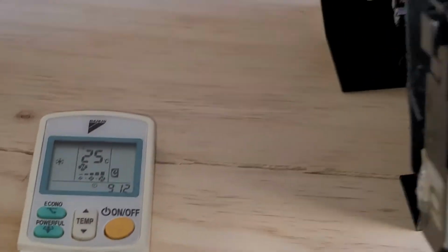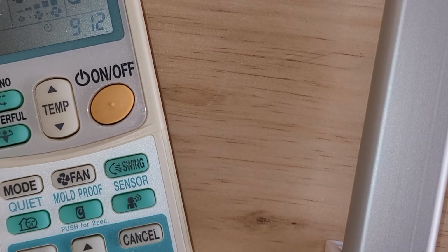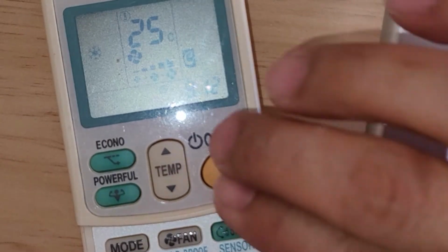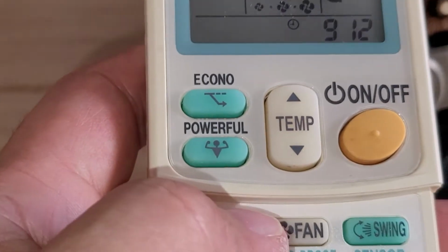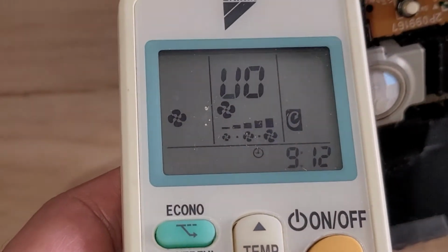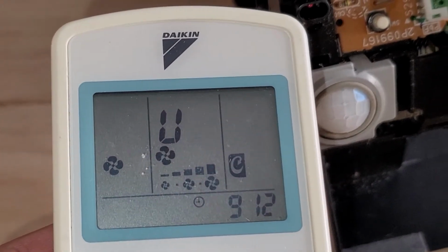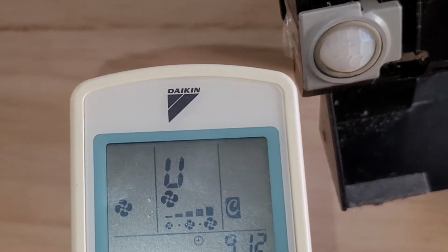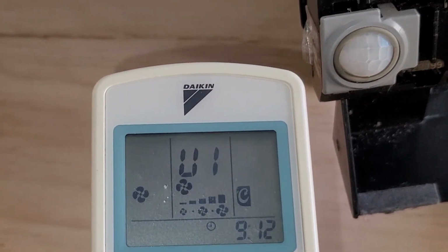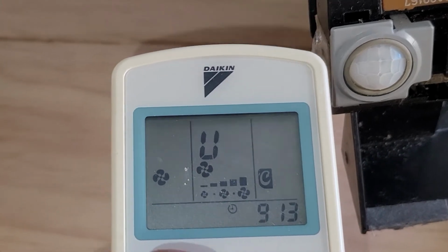We rested for too long, so the malfunction code got reset already. We're going to go into it one more time. It remembers the last one, so you stay at U. What I need to do now is press mode. Then it will toggle to the second digit. We repeat the same process. Now it will be a double beep. Double beep is no fault, it's not the malfunction.